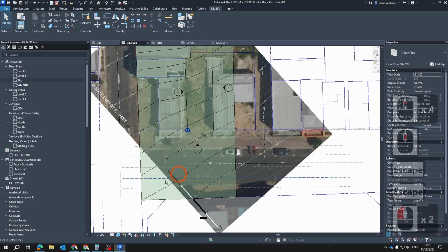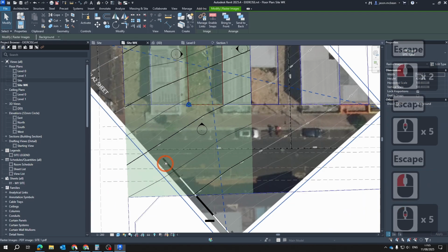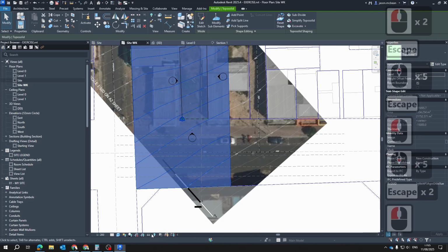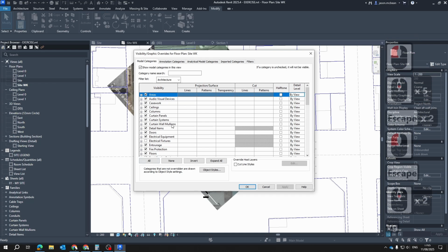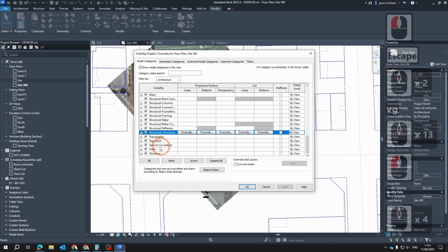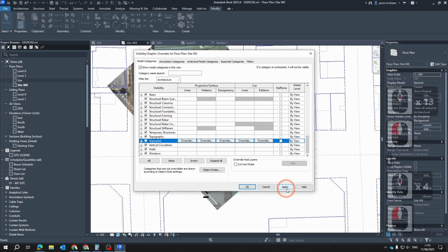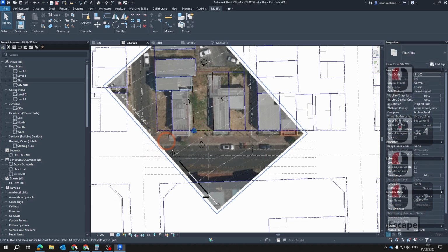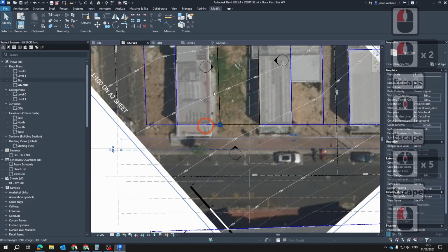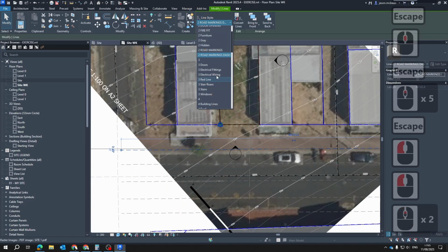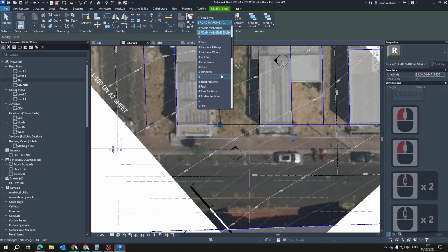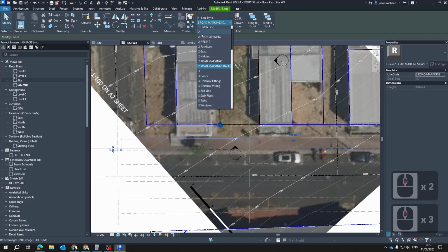So reset temporary hide. Let's just hide the topography for now. So hide that. In VG in your working view, just remember you can go to top of solids, hide it here, top of solid, press apply, press OK. Good. Now, this will become our curb line. If you don't have a curb line, you can make your own line types.